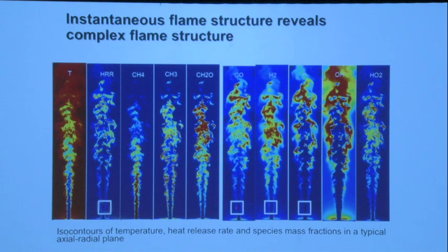That's also true of CO. There's hardly any CO, and H2 and H atom are kind of absent in the near field, or at very low concentrations. And we'll talk about that in a minute, and what happens when you have very, very strong strain rates and turbulence-induced stretch due to strain as well as curvature stretch. So when a flame's really wrinkled, its own self-propagation can create stretch that the flame is subjected to.